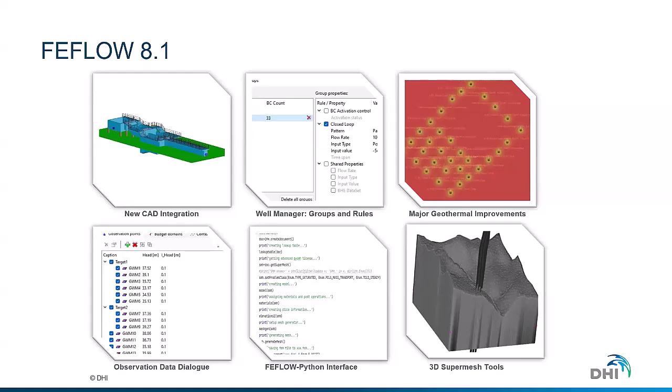The update has a number of different features, from CAD integration, a number of options in the well manager to create groups and rules, a lot of features for geothermal applications, a new observation data dialog, which allows you to control, as before, the observation points, but now also budget groups and content domains, new functionalities in FEFLOW Python, and several 3D supermesh tools, some of which I will use in the live demonstration today. This was in the release 8.1 last November.